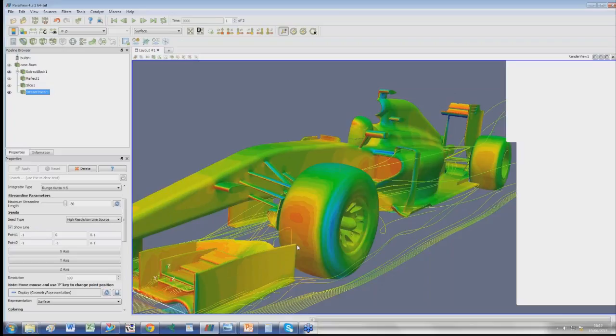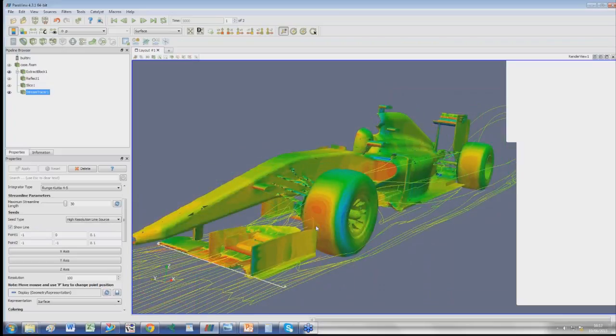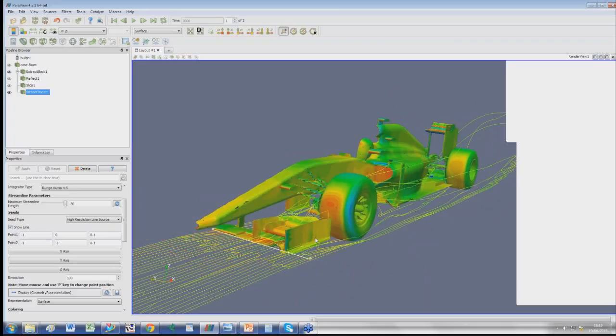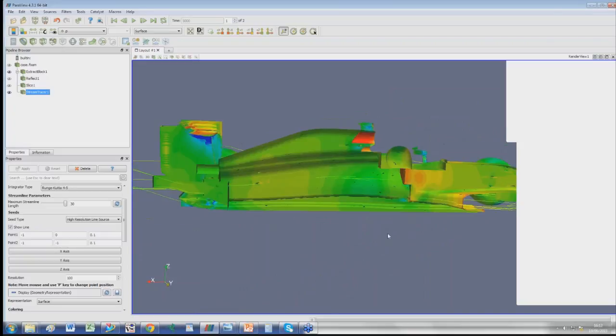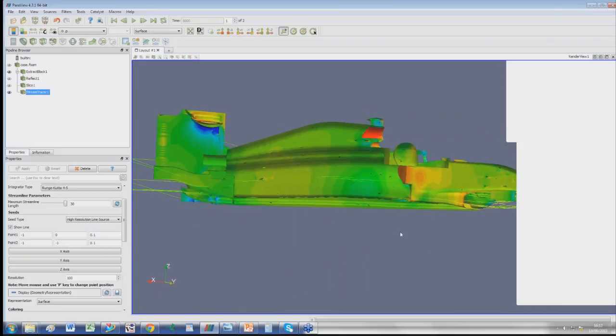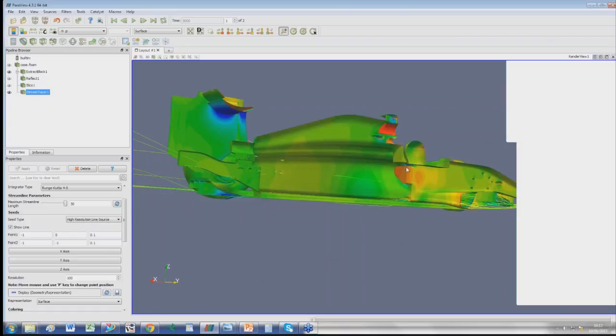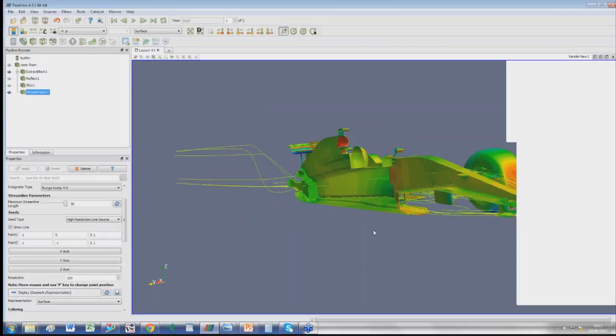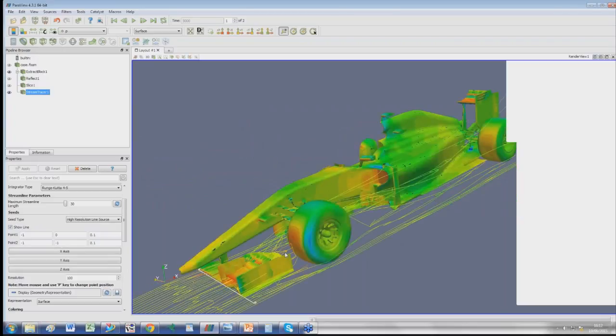Yes, Nick. Well, quickly, this very simulation we are looking at doesn't have an internal flow. You can see I'm looking at effectively behind or inside the car. Normally some flow would come in through here, but we've blocked the inlet and then go out here, but we've blocked the outlet. Simply because we wanted to save some mesh size, and make the model a bit more simple so that it's much easier for you to download and play with it. But when we would develop the car, we would actually simulate all the internal flow.